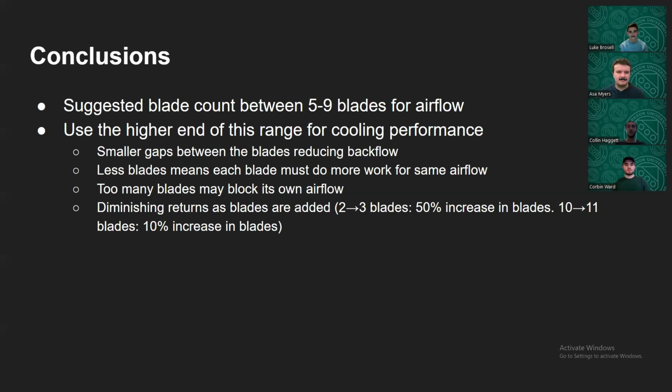We learned that the smaller gap between blades reduces backflow and can increase static pressure, and that too many blades may block its own airflow. While blade count did have a noticeable effect on performance of our fans, we would deem a range of values to be acceptable. This still meets our goal of determining how many blades should be used on a PC fan and how changing the blade count affects volumetric airflow.